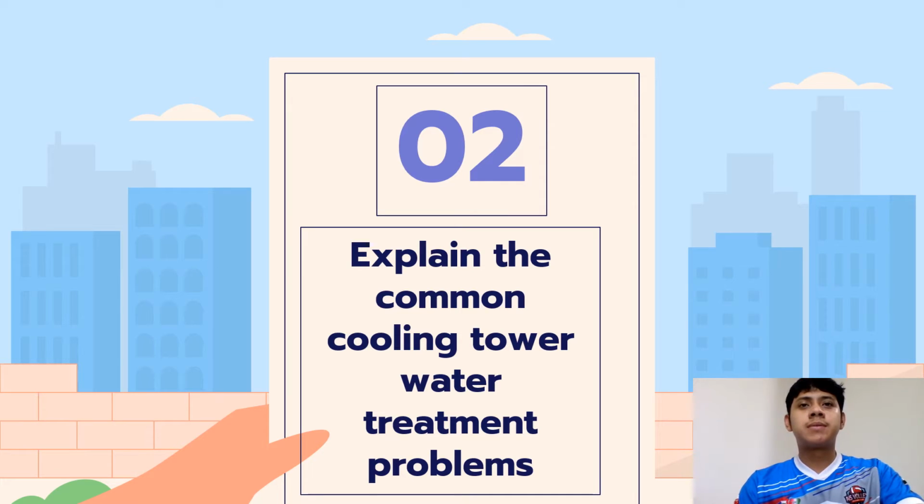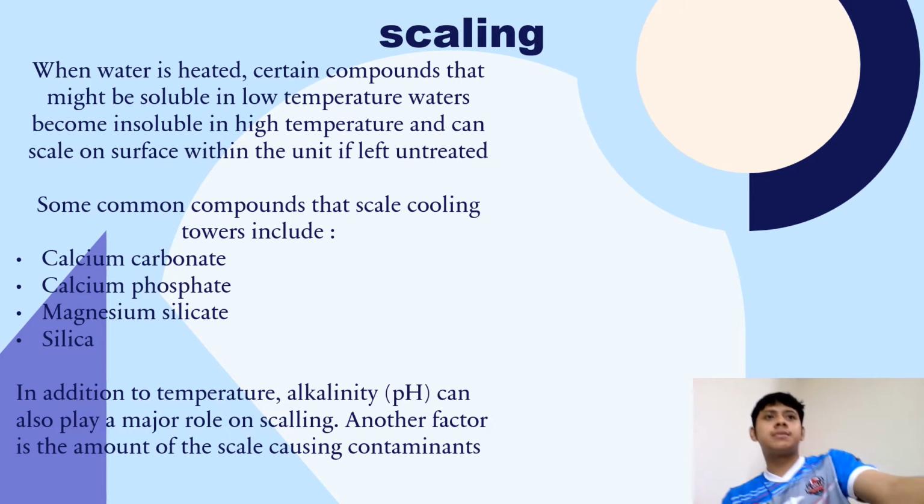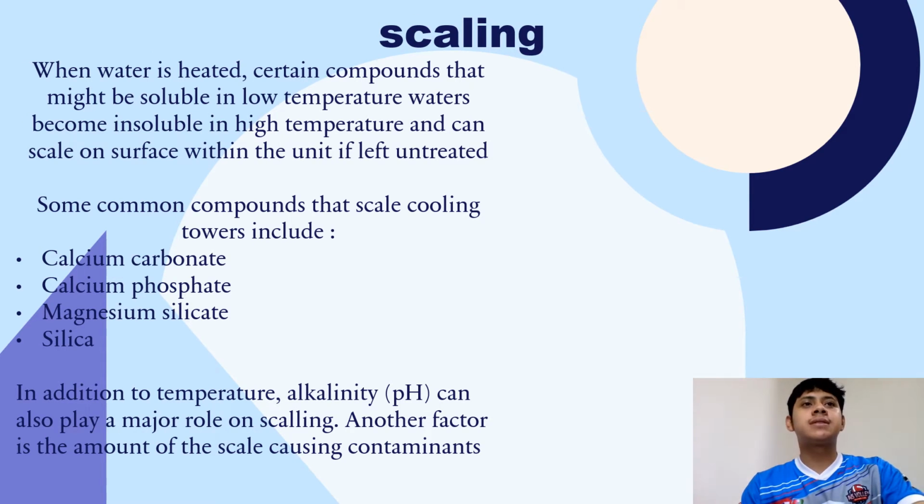So I'm gonna explain about the common cooling water treatment problems. So first is scaling. When water is heated, certain compound that might be soluble in low temperature waters become insoluble in high temperature and can scale on surface within the unit if left untreated.